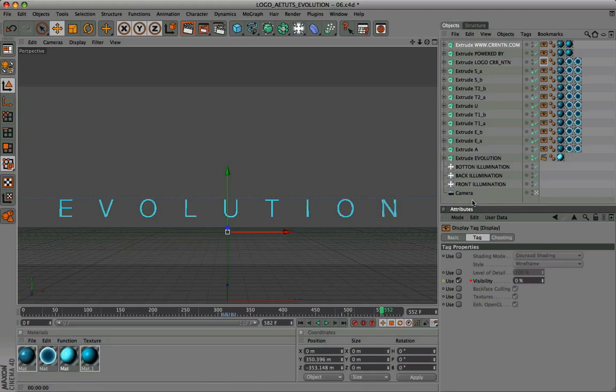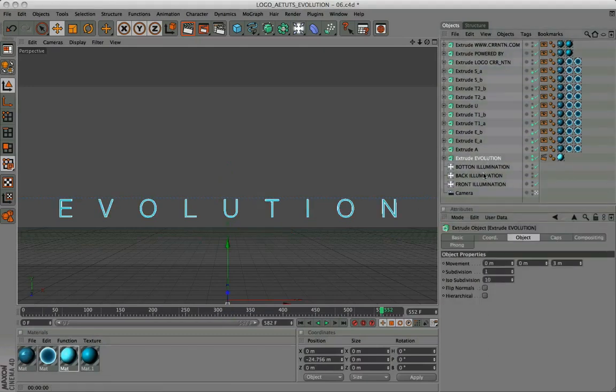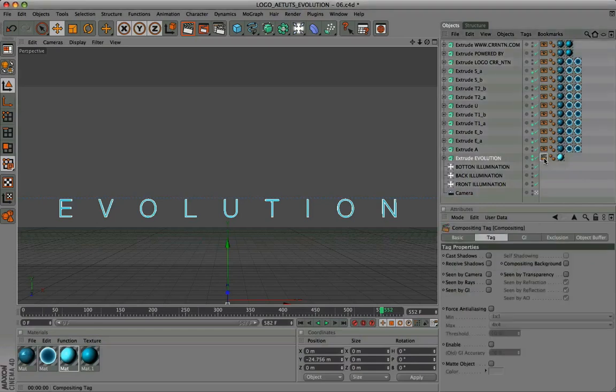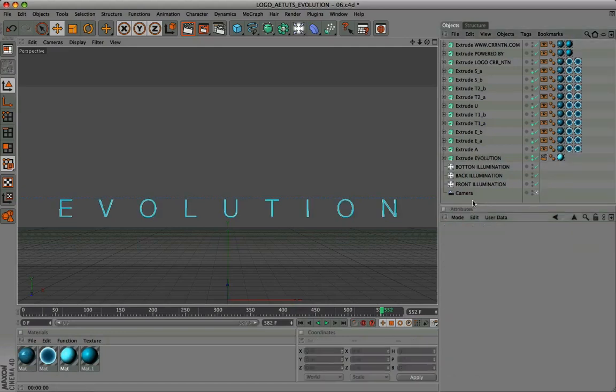We're going to create two renderings. The first with the VFX logo without text evolution, and the second with the text evolution. Just toggle, in compositing tag, scene by camera. We will then have an animation reference of text evolution in After Effects. Because the text evolution with the intermittency effect is created inside After Effects, so we have an exact reference to Cinema 4D.